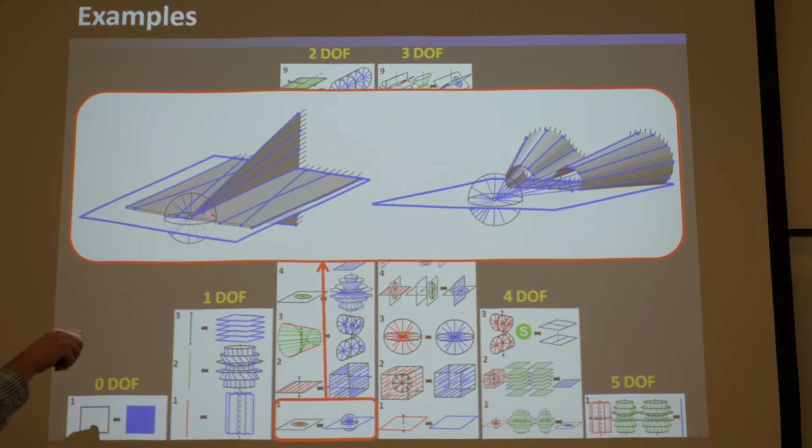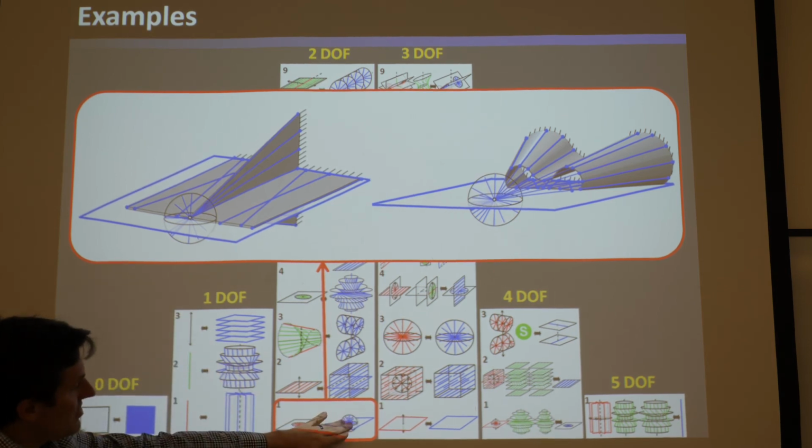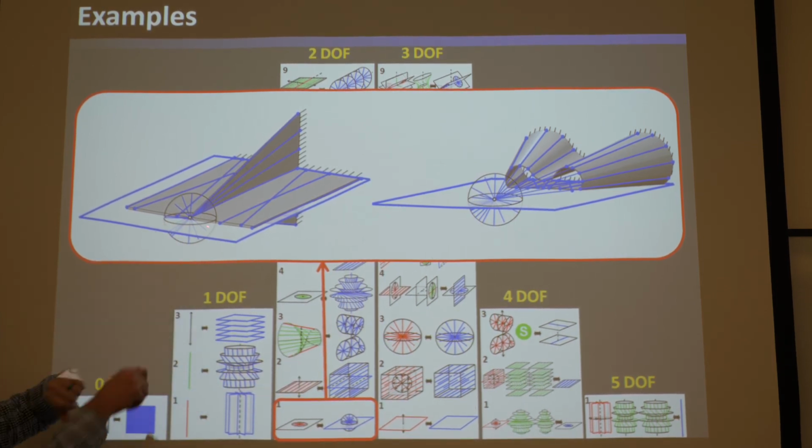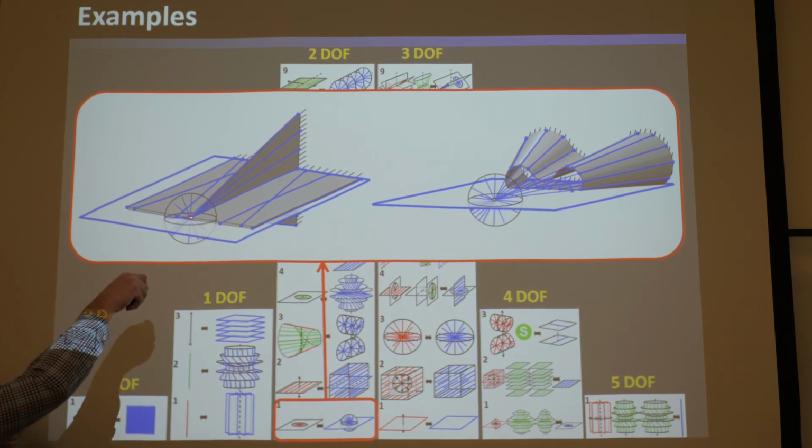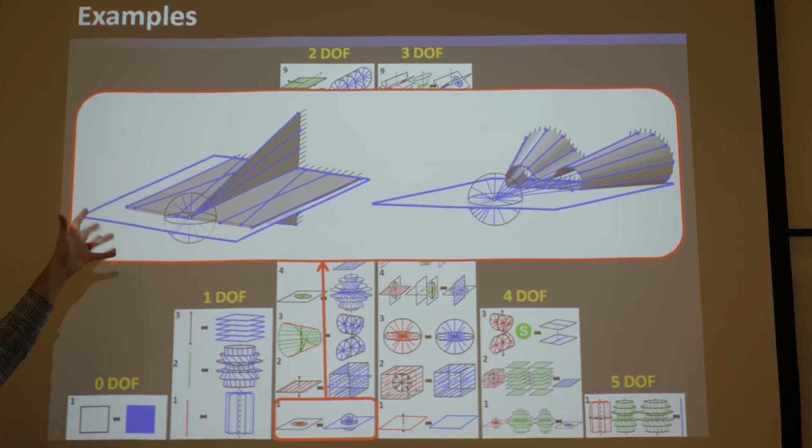This is basically like a V blade flexure and then just a normal blade flexure kind of fused together. You can see as long as you ground this back edge that's hatched to the ground and then this front edge right here to another stage, you could satisfy all the parallel conditions of an element. You could draw blue lines that directly connect those without exiting the geometry, and you could fill the entire thing all blue. And sure enough, it would have enough independent blue lines in it that it would achieve this guy's freedom space, and it would have a disk centered right there and in this plane. And that stage would move like that.